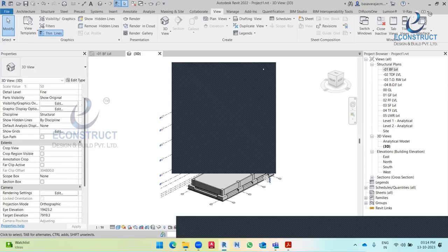Like that, depending upon the elements which you are using and depending on the levels which you are providing, you need to set the view range. Okay, by default it will take some values. No need to set those values. If you want, you can change those values. If it is not visible, we need to adjust. Fine. Okay.